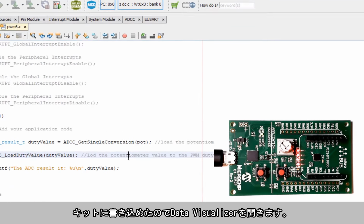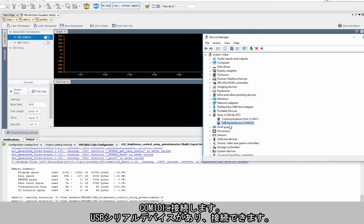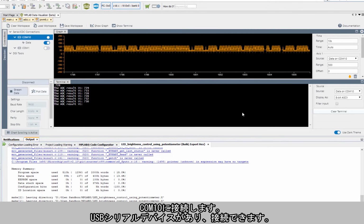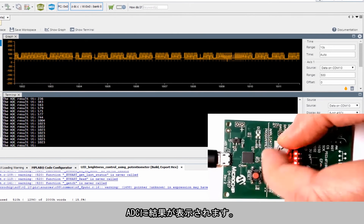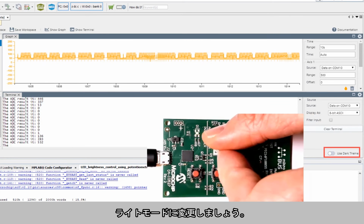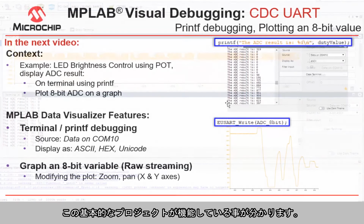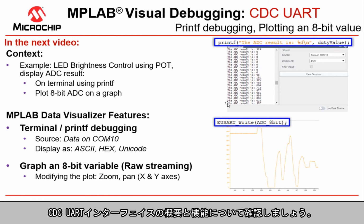Okay, our kit is programmed, and let's open the data visualizer, connect to, if we check COM10, we have a USB serial device, and we can connect. We have some results on our ADC. We can change this to a light theme, and yeah, so we have the basic project working. So using this project, there's another video where we go further and explore the different options available with MPLAB Data Visualizer and Visual Debugging. So we're looking at the CDC UART interface and what we can do over this.